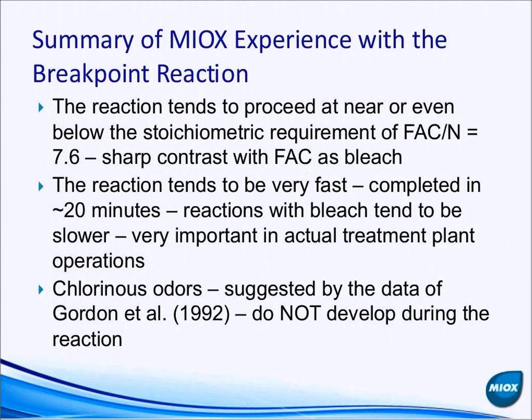So the summary of our experience of the breakpoint reaction, some take-homes, is that the reaction tends to proceed at or near, or even in some cases slightly below, the stoichiometric requirement of 7.6, the so-called ideal dose of 7.6, which is in sharp contrast with free available chlorine as bleach. The reaction also tends to be very fast, completed in approximately 20 minutes or even less, whereas reactions with bleach tend to be much slower, which means it's much easier and more reactive to control in your water treatment plant.